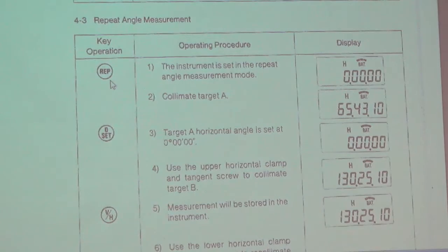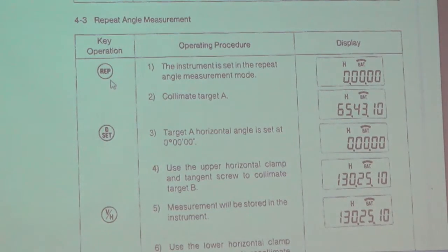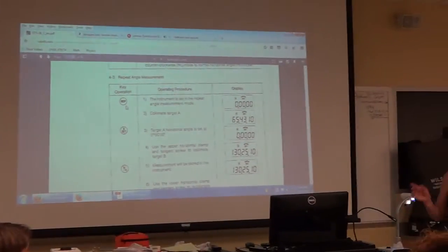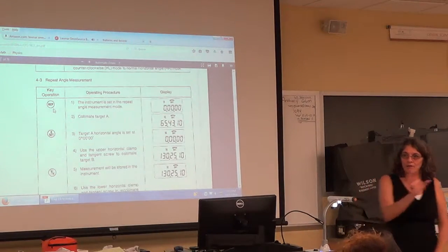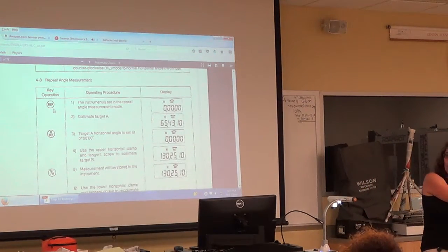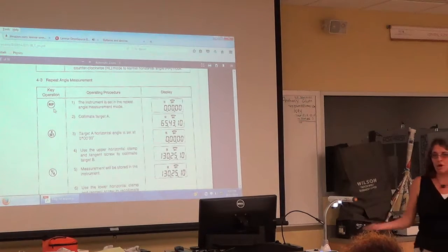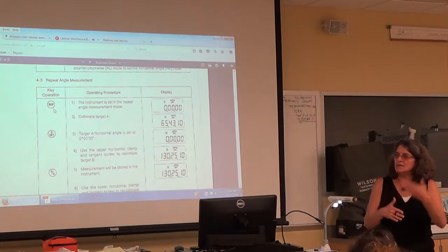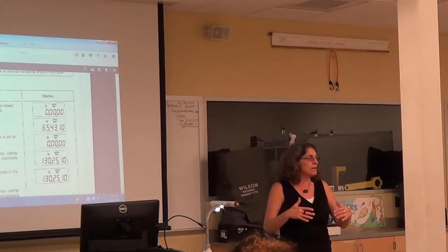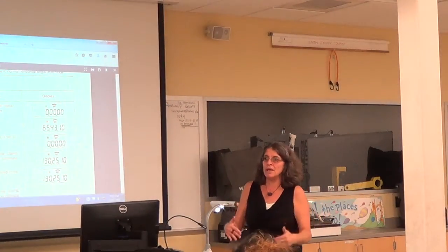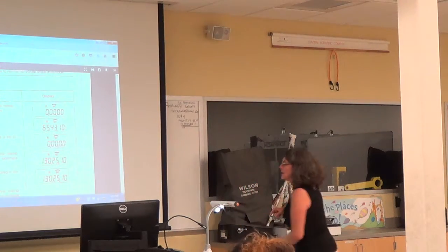So you type L for line, and now it says, where do you want to draw the line from, right? And then you could type END, the end point of, and then you could find the end point of a line, and then it says, where do you want to draw to? You get it? So that END is a command inside a command. I was in the line command, and then I told it I wanted to pick the end point. This is the same thing.